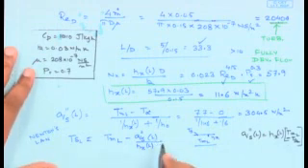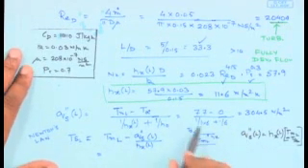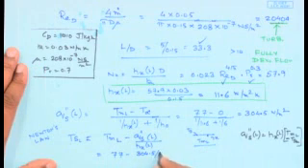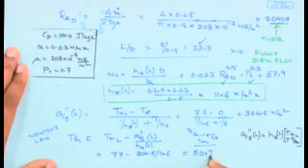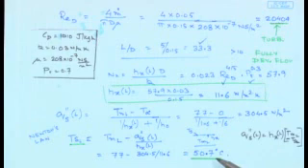Once you put the values in here, T_m,L as we know is 77 minus 304.5 divided by h_x, which is 11.6, this would turn out to be 50.7 degrees centigrade. So this is the temperature at a distance of 5 meters.